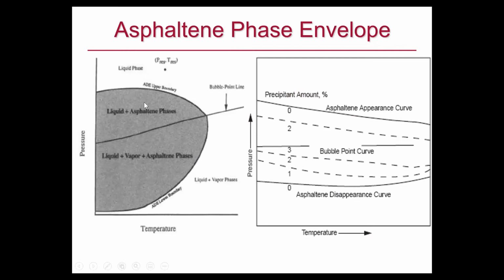This is the upper asphaltene point. This is the bubble point, and this is the lower asphaltene onset point. The reason that asphaltene goes back to solution is because above bubble point, for example, reservoir pressure is here. You don't have asphaltene problem up to here, and then starts the asphaltene upper point. And then at bubble point is normally the maximum amount of asphaltene that can form.